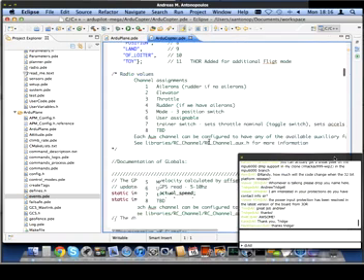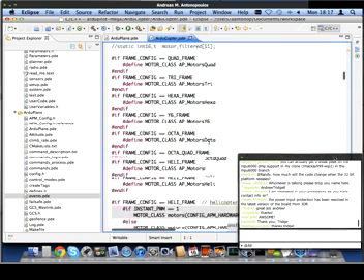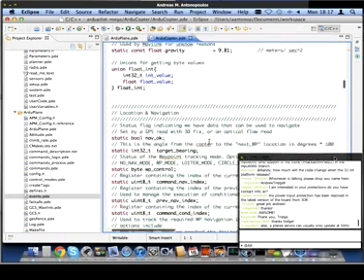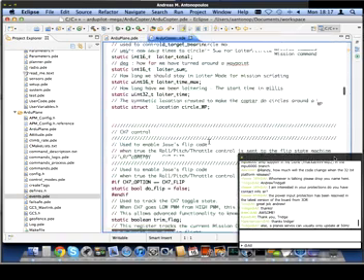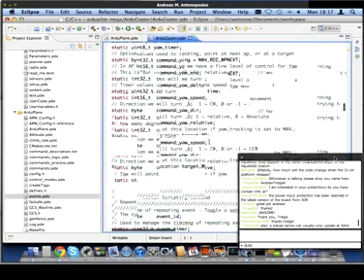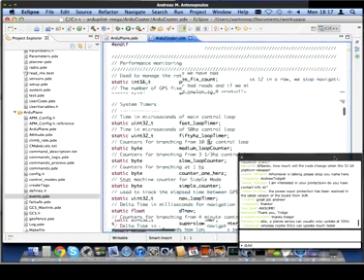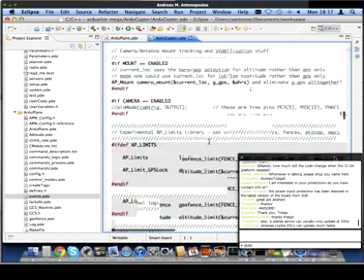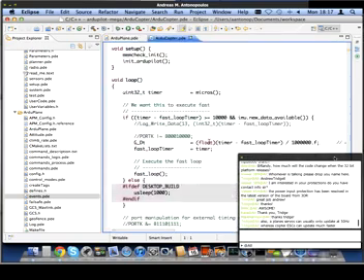Obviously, a plane is inherently aerodynamically stable. If you stop doing stuff, it generally just continues to fly. With a copter, if you stop doing stuff, you are 5 milliseconds from falling out of the sky. So that's why you'll see that some things work slightly differently. Of course, the loops are running at higher speeds, and here we have a much faster main loop. And I believe that's currently called at 100 hertz.